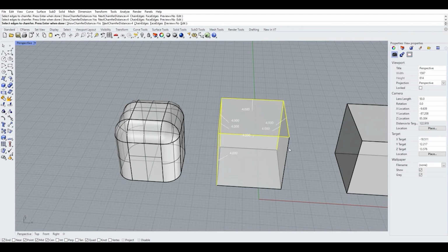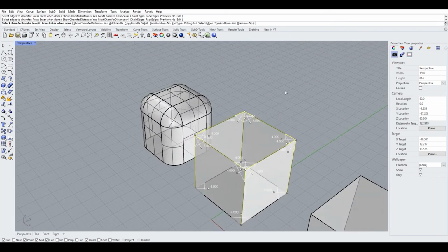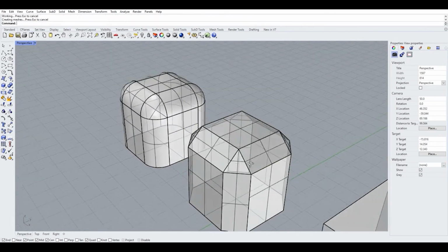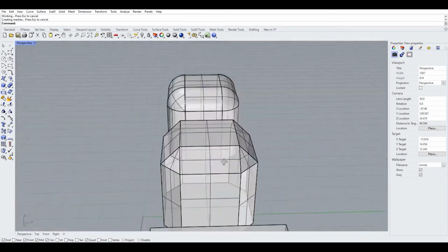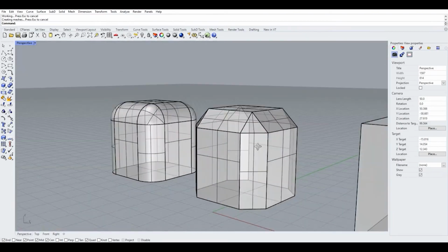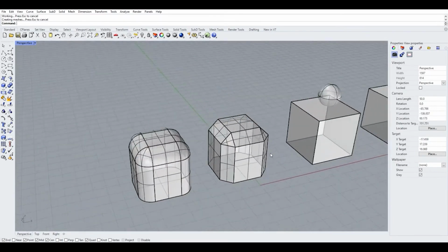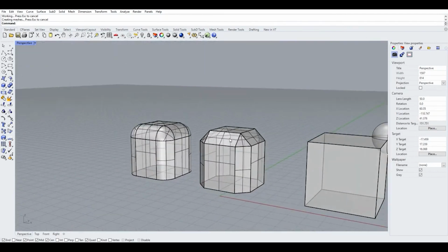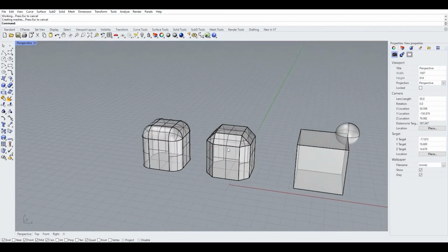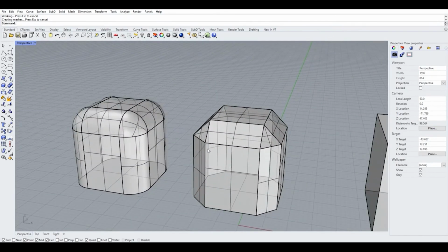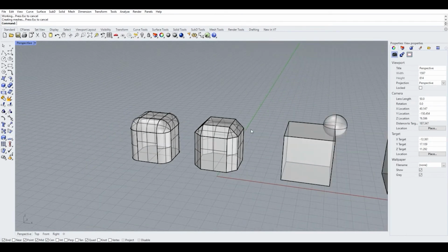Exactly the same as I did with the previous one. Hit enter. And you'll see it cuts all of those corners at a 45 degree. So that's a handy thing if we don't want to round them out exactly or add a little bit of extra geometry. That's a nice way of doing it. If we design for machining or CNCing, this is an easy way to create edges that have been finished, that are still sharp, but have been finished so they're not sharp and will cut you.